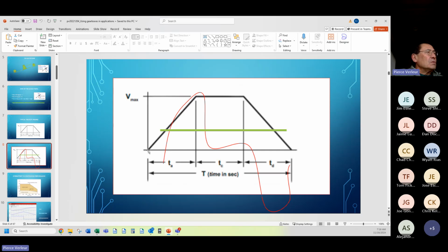But when you go acceleration, your amperage, and therefore the torque required to get to speed, is going to cause a peak. And therefore that affects the peak values allowed on the components you are selecting. So in this particular case, while accel and decel have high values of torque and therefore power, therefore strain on your system, running at speed is, as you can see, somewhat easier on the system.